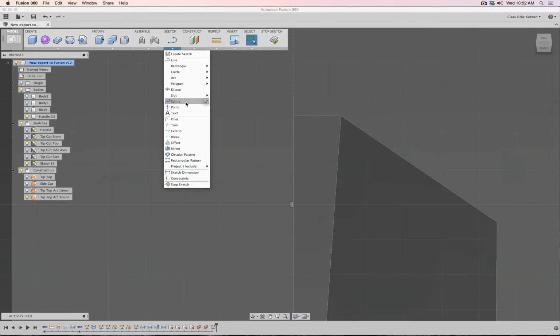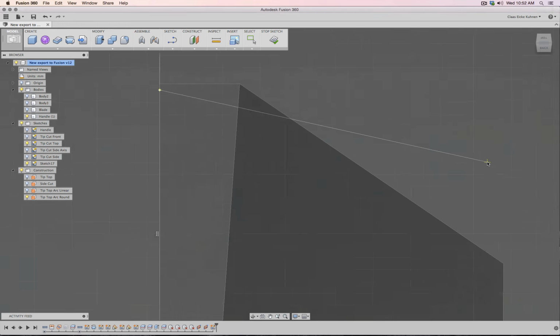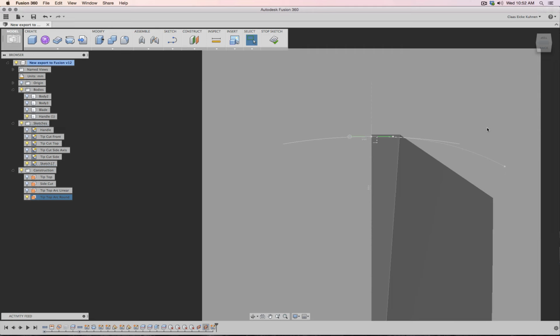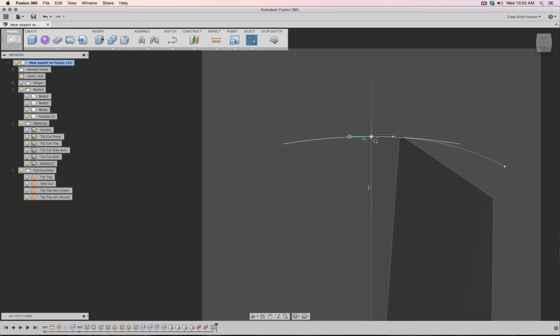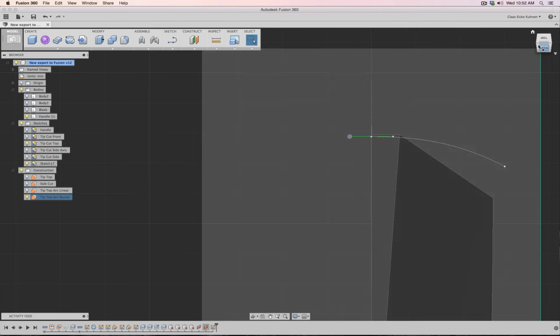So I'm going to do it this way with a spline. And let's see how many points we go out. Let's select this one. Click, OK. And then here, those handles I make horizontal. And there you can see that I have a nice even arc, and it's actually tangent to the mirror plane. Probably sounds familiar to Alias. Okay, good.